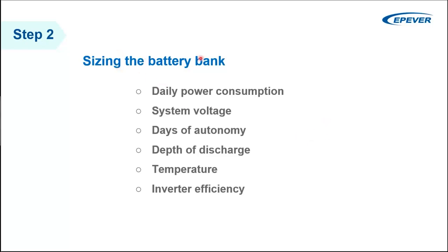So this is the step of selecting the battery, but at the same time, you should keep an eye on what charge controllers and what kinds of inverters are available in your market. If you decide to use a 48 volt system voltage, then the inverter must be available for you in the market to purchase and use.